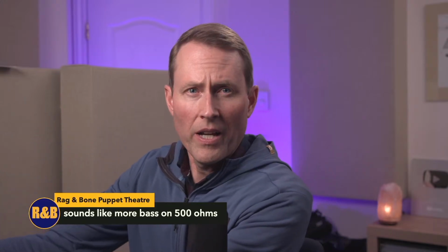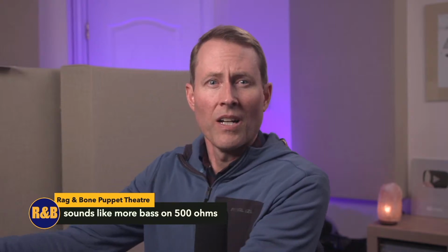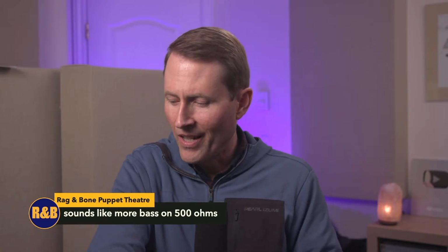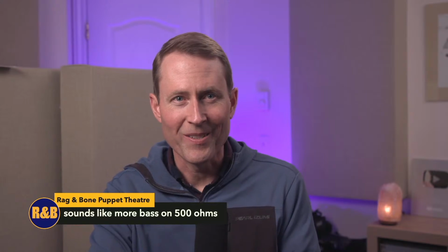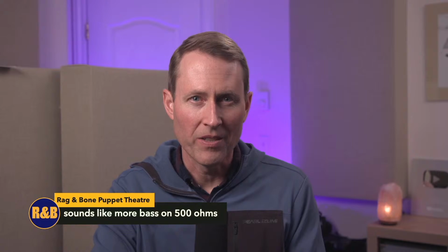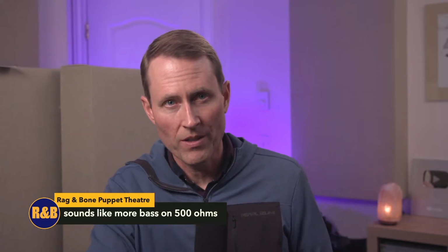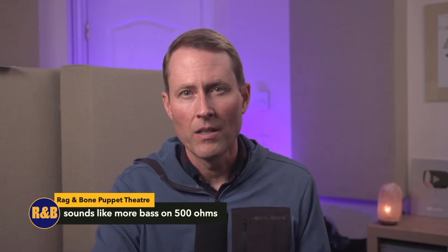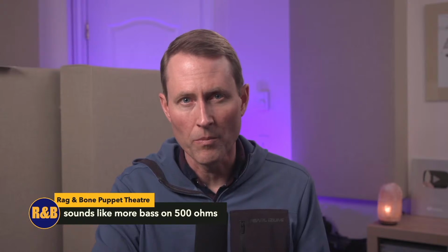Okay, back on my regular mic here. And okay, sounds like more bass on the 500 ohms. Yes, indeed. And that's a pretty common type of thing that you'll see. I think in part, one of the reasons why, especially in the music world, you'll find that a lot of people like the vintage gear because they claim it has a warmer sound to it. Maybe that's part of it. A lot of times the vintage gear will have lower input impedances than the more modern gear.